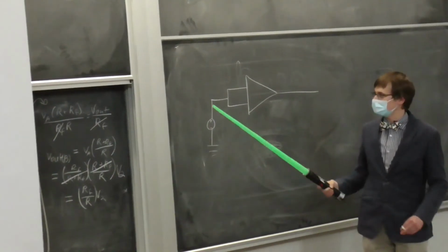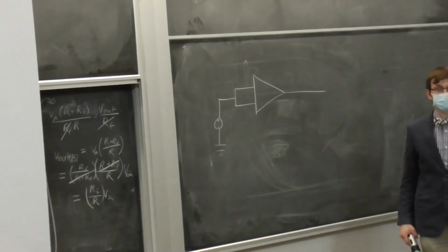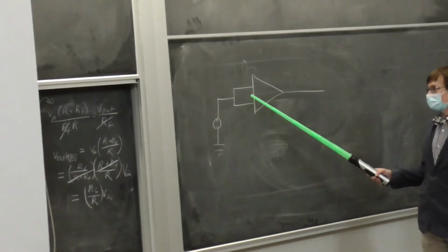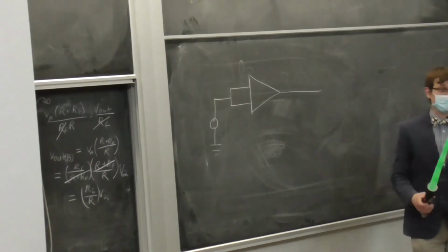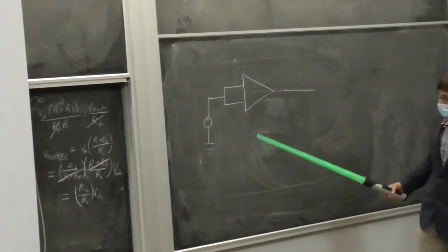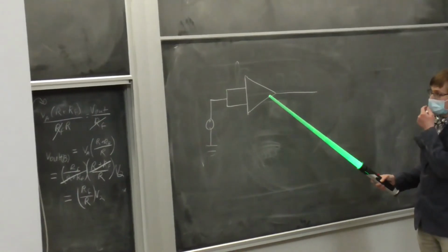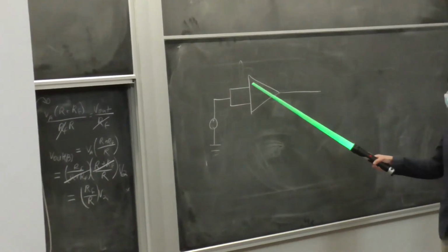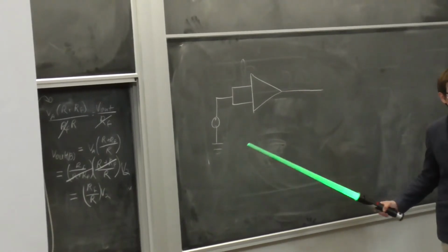In theory, there should be no output, right? Because the operational amplifier amplifies the difference between the two signals. They are actually being held down together instead of just being approximately together as we normally assume with operational amplifiers. So in this configuration, you end up with what is called common mode noise. It's called common mode because both of these input leads are connected to a common source, right?